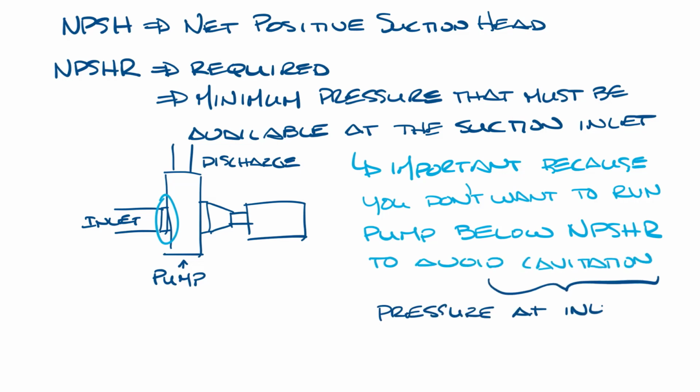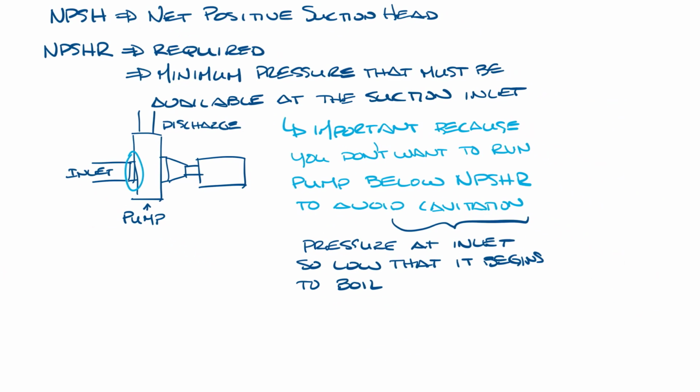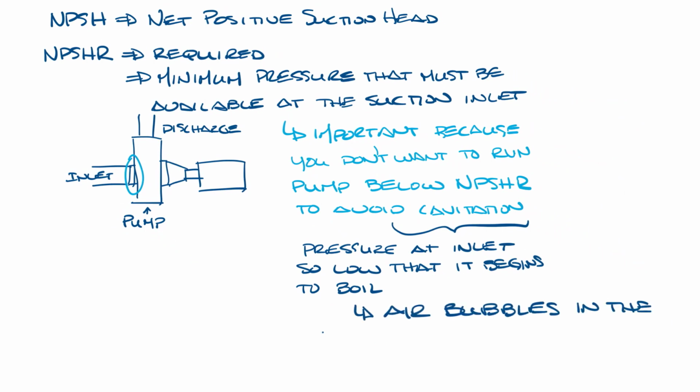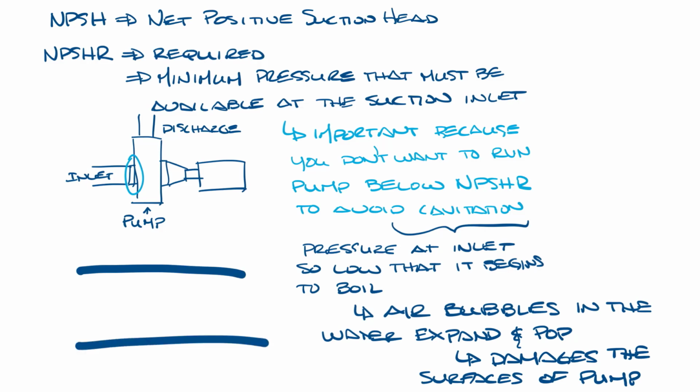Cavitation is the point where the pressure in the inlet of the pump gets so low that the water begins to boil. Let me make a little bit more room. When this happens, air bubbles in the water expand and basically pop, damaging the inside surfaces of the pump.